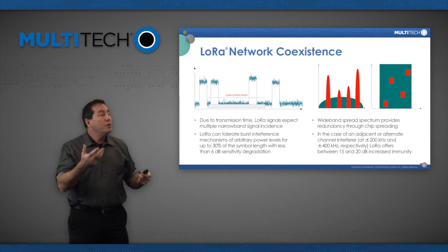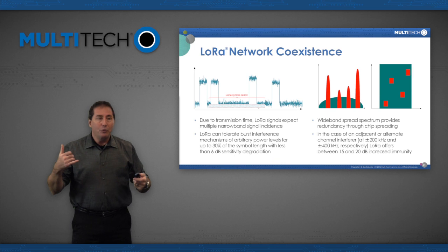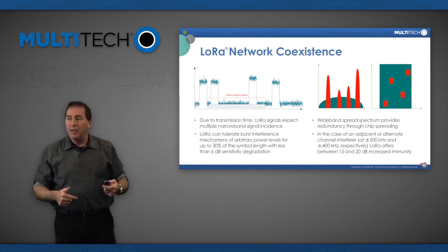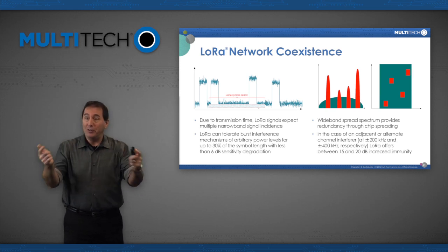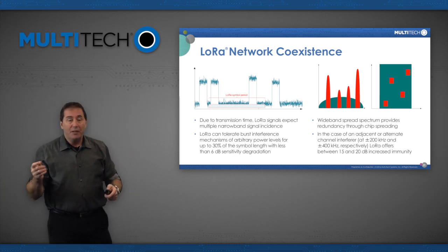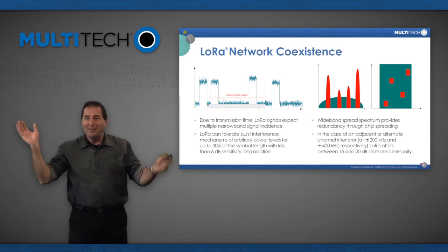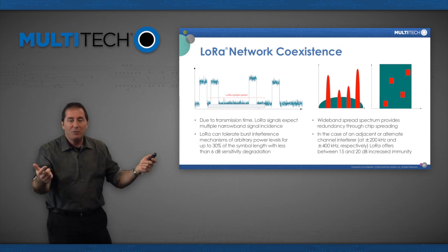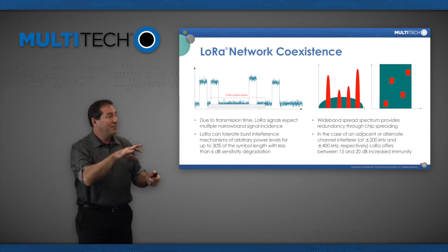So what does that mean, though, to your customers? Well, what that means is that we're using the ISM bands, and those are free, and anybody can use them. And so when you use LoRa in the ISM band, other people who are not using LoRa are interfering with each other and not being very happy about it. Oil and gas industry is a big problem because they're all using FSK radios. And those really just bounce off all the metal and they go nuts. You put a LoRa radio system in that environment, it works great, because the other systems don't even see LoRa.